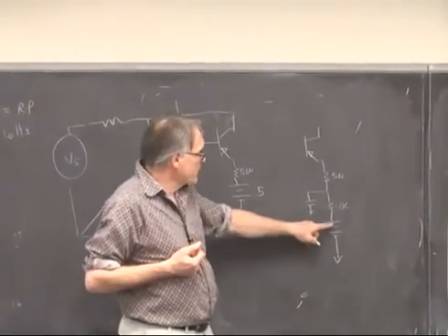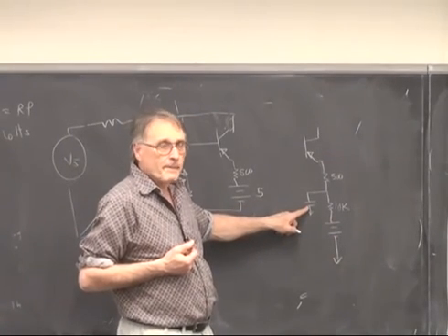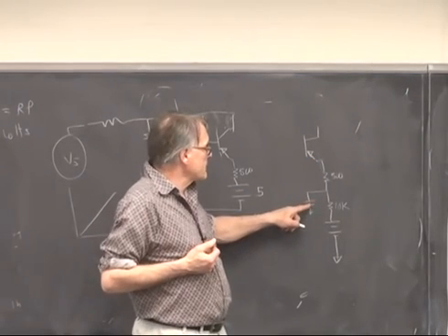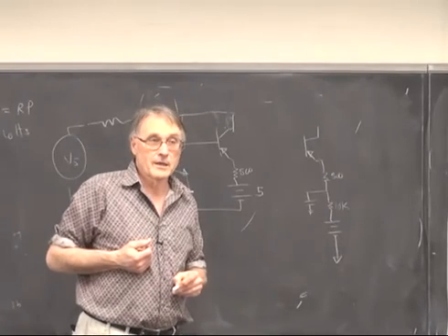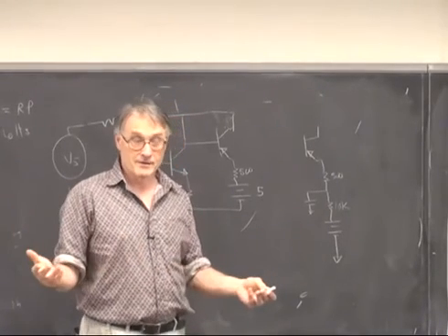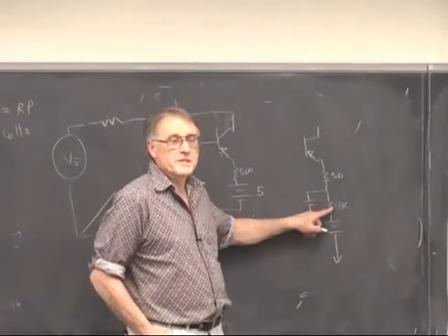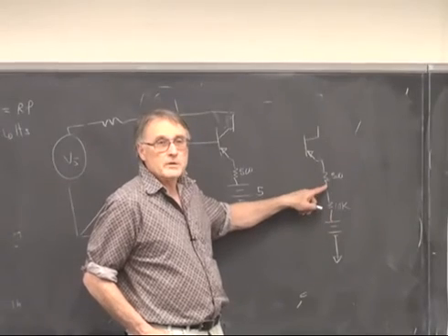The battery would trickle charge this capacitor when it was resting. When this whole system is turned on, it sucks the charge out of this capacitor almost instantaneously. And then there's no more charge because the very large resistance here causes such a large voltage drop.